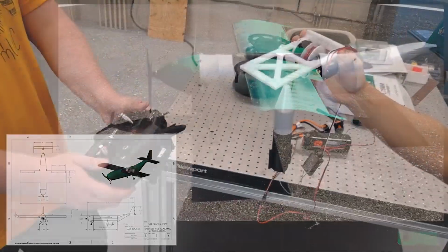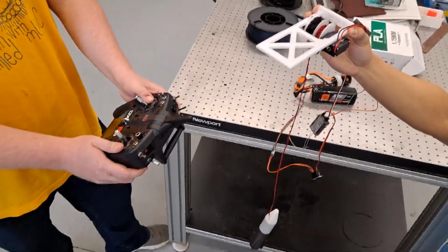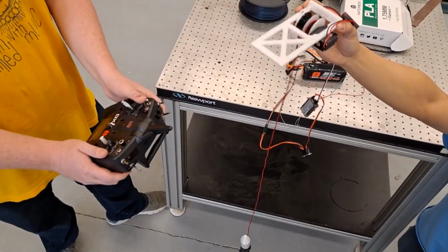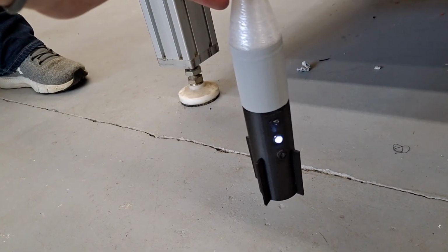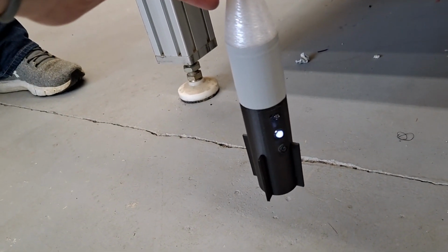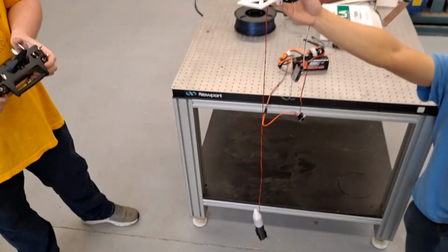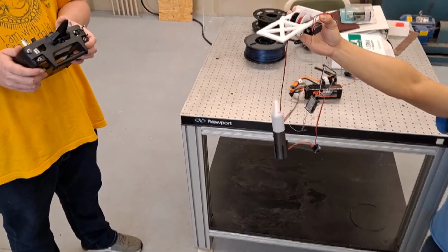For the ground mission, we showed a functioning deployment and retrieval mechanism with an operational sensor light pattern. The deployment servo's 3 outputs, which are to turn clockwise, counterclockwise, or stay at rest, are determined by the inputs, which are the 3 possible positions of the stick switch on the transmitter. The Channel 6 port on the receiver sends these inputs to the winch controller, which then outputs it to the winch deployment servo.